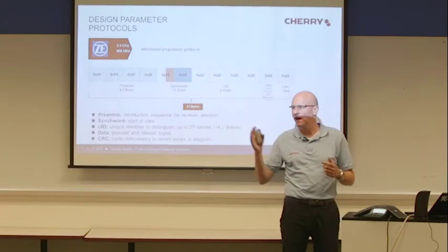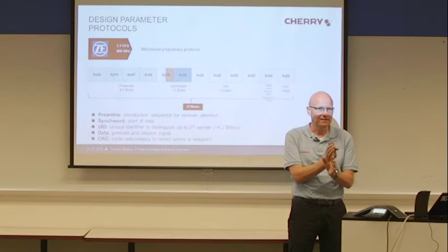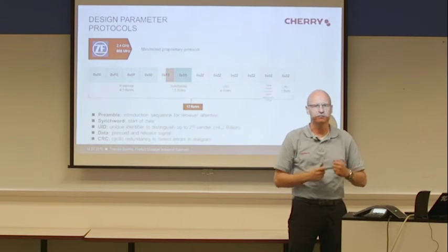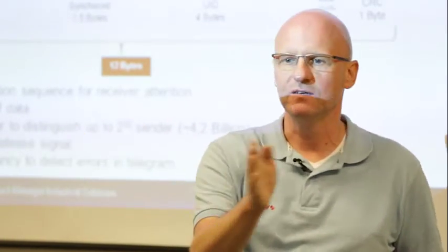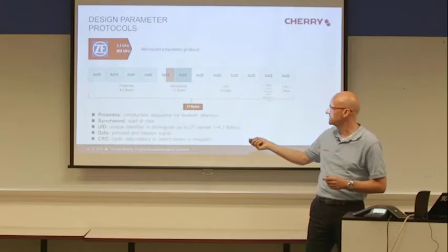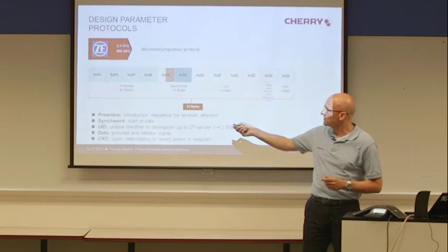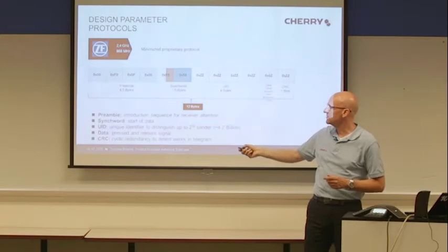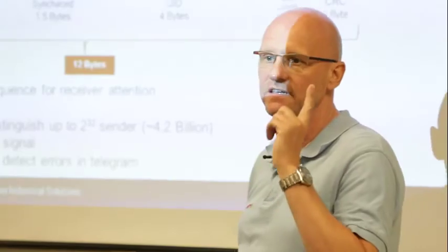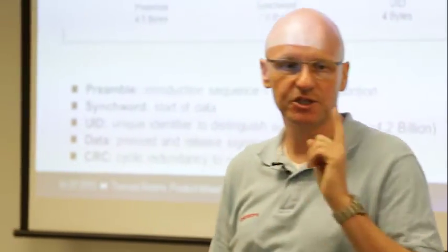So if another sender uses the same RF frequency channel, the receiver gets all this information. And the receiver has to decide what information is for me, what is important for me. For this, the preamble is the right thing. From the structure of the preamble, the receiver knows, oh, that is a signal for me. It's from the Cherry switch or a Cherry sender.